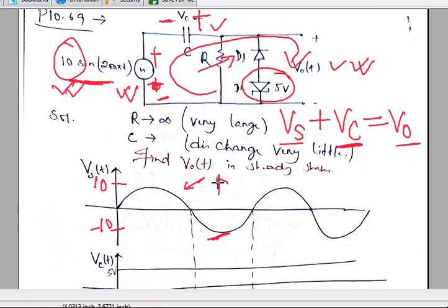In the lab also you have done this kind of circuit. I guess you have done the clamper circuit. It is nothing but a clamper circuit, but you did not connect this Zener diode. So the entire waveform got shifted by Vm, but here one Zener diode is there, so it is going to be shifted by voltage Vm minus this voltage. Here it is 5, so it is going to be shifted by 5 volt only.